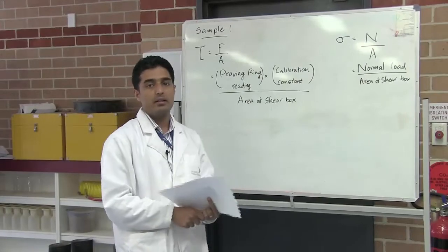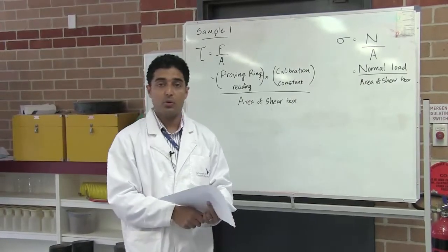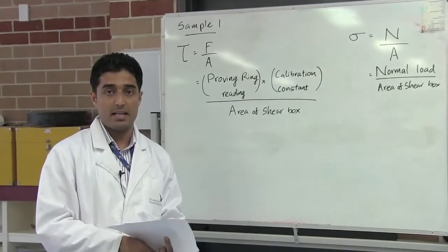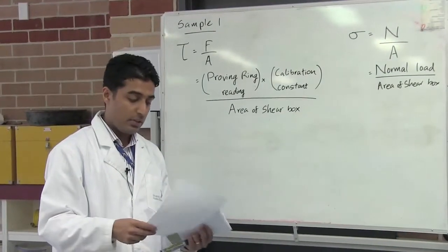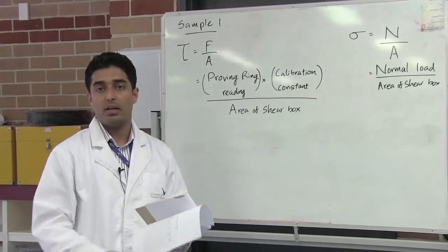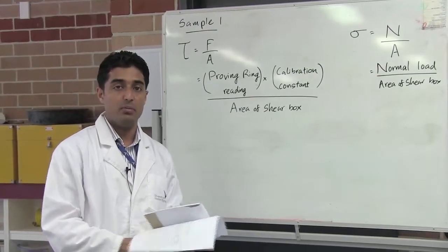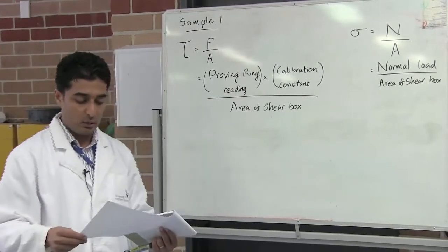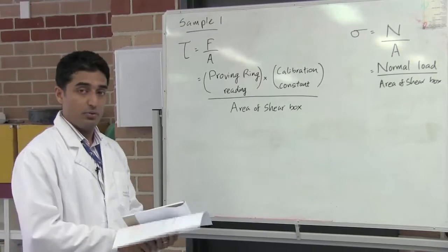So once you conducted the shear test for all 6 samples, that's 3 loose sand samples and 3 dense sand samples, you can fill out the data sheet number 10, and from those data you can fill out the data sheet number 11. You have to fill both the data sheets before you leave the practical. I'll show you how to do a quick calculation to calculate the shear force.